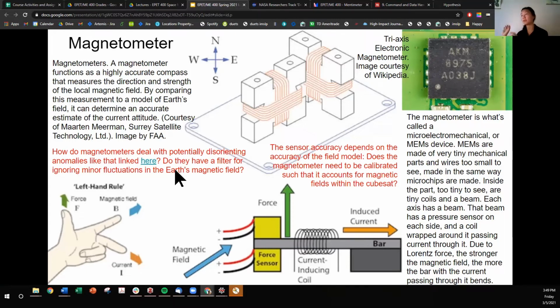So before you approach the South Atlantic anomaly, maybe you could go into safe mode and shut down your instruments and major hardware, go into kind of a sleep. And then once you exit out, you can turn things back on. But those can be worked around.